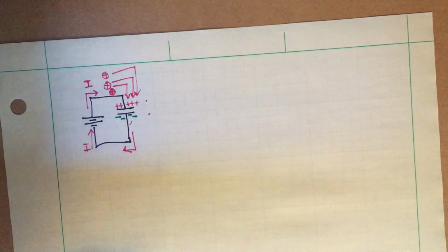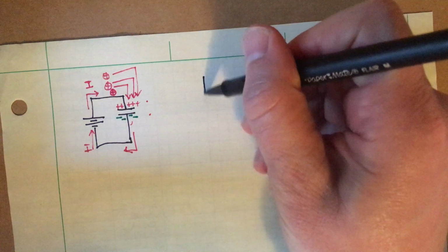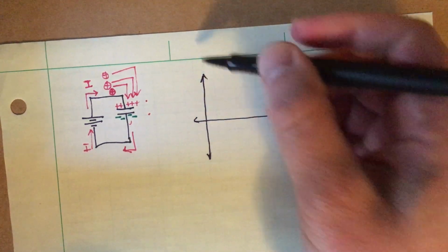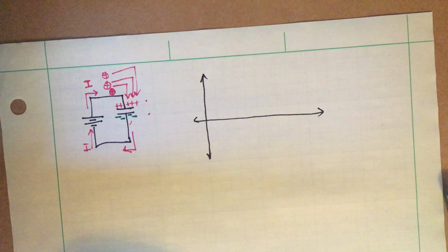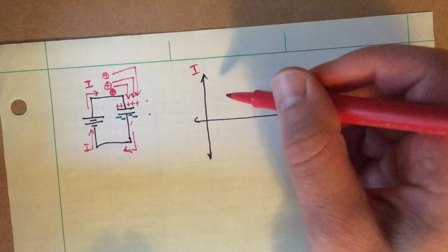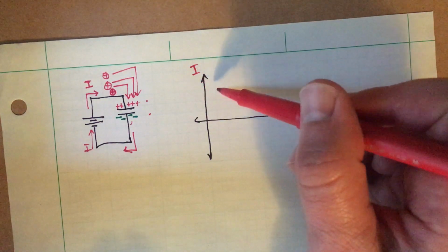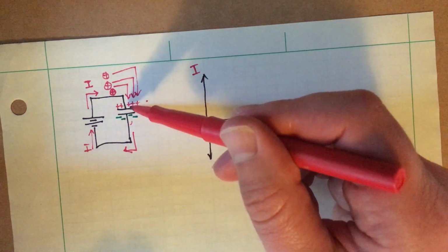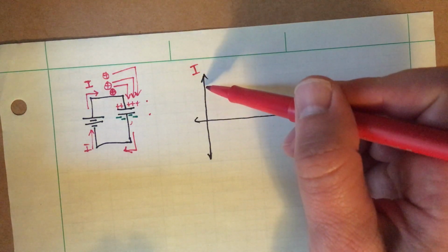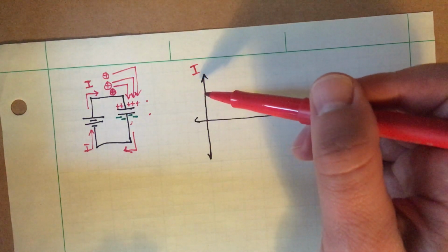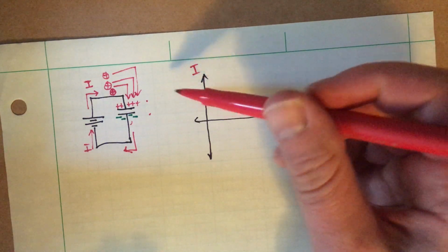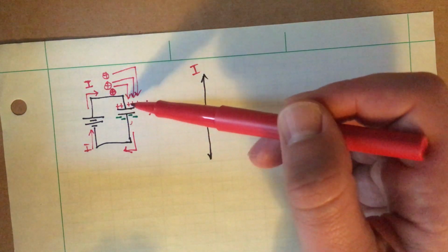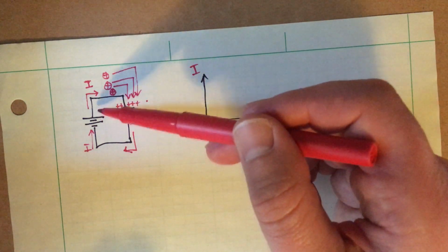And if you're looking for what that looks like in terms of voltage and current in this simple capacitor-battery circuit, if we put current in red first, we start at a particular value. At first there's no charge on the capacitor, and so current is going to flow really well, but only for a moment, and then you're going to have to spend energy to shove more and more charges on here. As you accumulate charge, there's going to be this opposing voltage on the capacitor that opposes the battery.